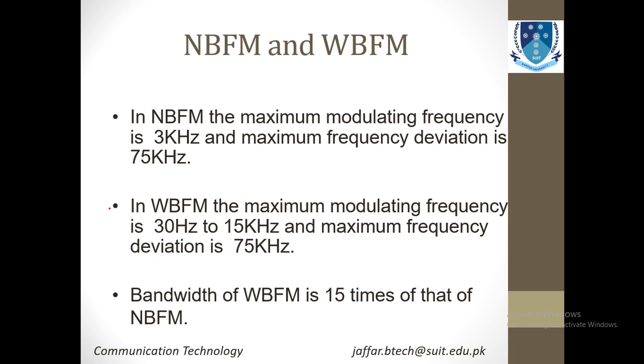So if you talk about NBFM, it has the same analogy with AM, because it has a limited number of two sidebands. But in wideband FM there is a multiple range of sidebands. You have infinite sidebands, and the requirement increases because of the bandwidth and because of the power.